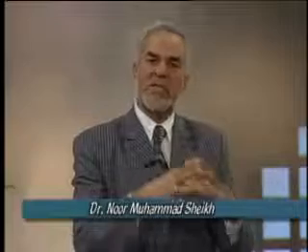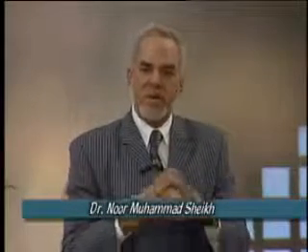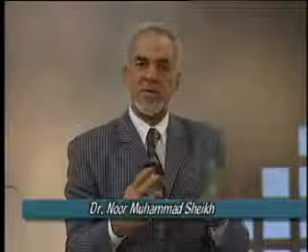That means the address alignment would not be required, and by multiplexing at one time, we take up 8 bits from the data bus, and in the next reading cycle, we take the next 8 bits from the data bus. This concept is called the data bus multiplexing. Let us see this illustration in the next slide with the help of an example.